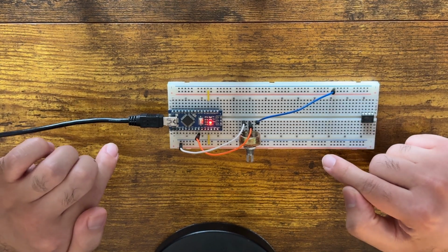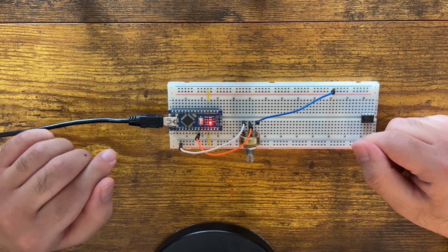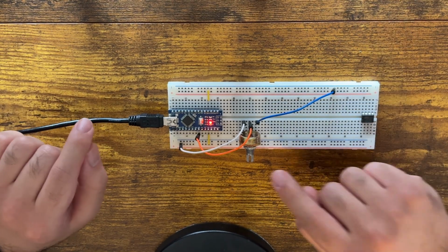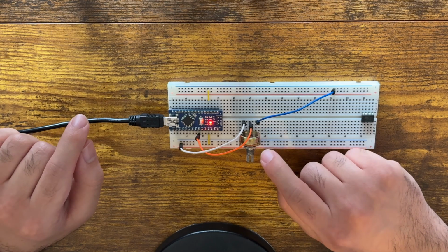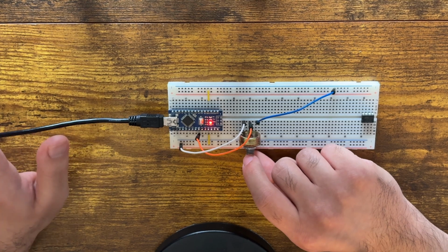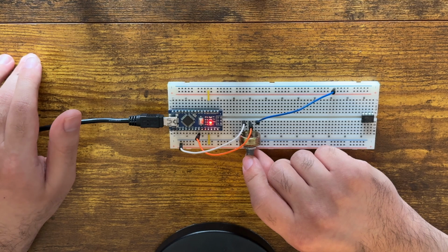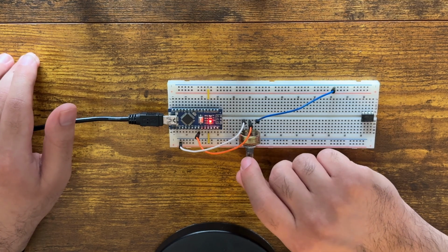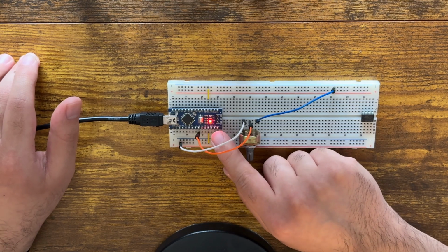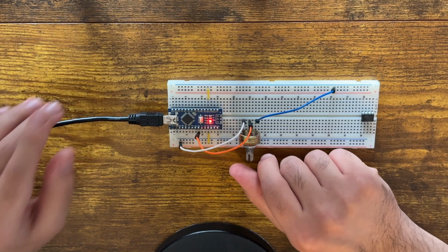And inside this microcontroller we already have this ADC, analog to digital converter. So we will find out how to use it and how we can drive this potentiometer, especially read this potentiometer. For example, if it is below some value, I set it to be below 512, and where these values come from I will tell you in a bit. So if it's below 512, that means this built-in LED that we drove in my previous videos will be turned on. So let's try that.